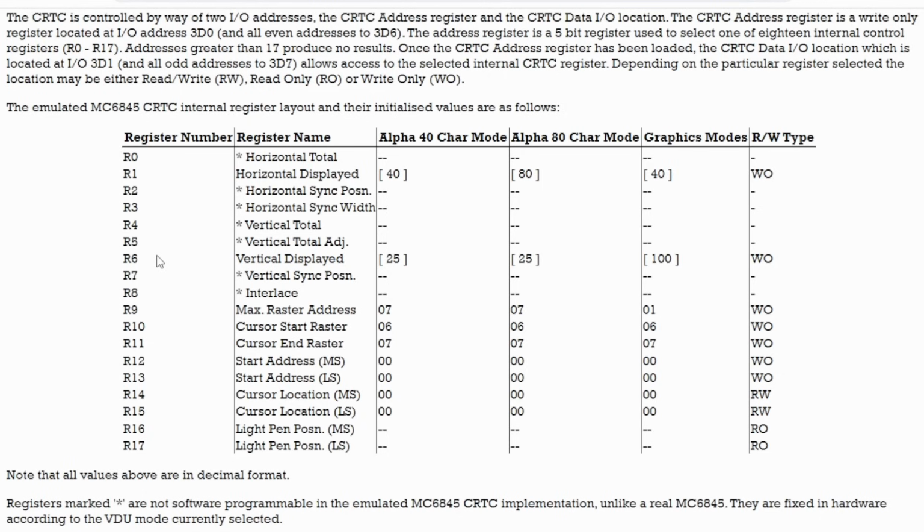I thought maybe it was just so that you could change a value with a single write instead of having to do 2, but I can't see how that would work, and in any event, on most PC systems, not all, you can do a 16-bit write to 3D4, the low 8 bits will go to 3D4 and the high 8 bits will go to 3D5, so you can kind of do it all in one operation. It's a little bit slower, but it's still possible. And so I don't really see how that would be different here.